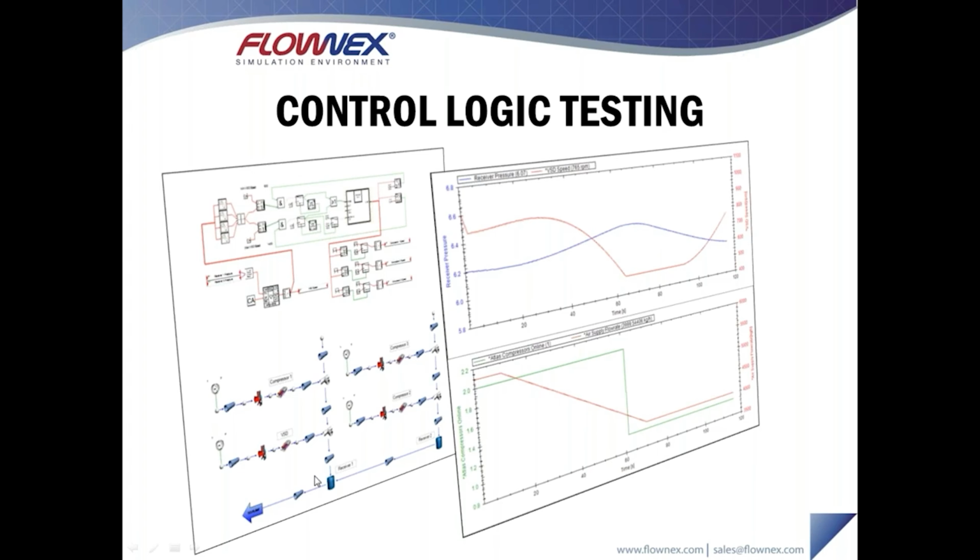load changes, or perhaps the pressures inside of your actual compressed air receivers are not constant, and you want to try and optimize that. You could look at better tuning on the PID itself. So a network like this becomes very practical.